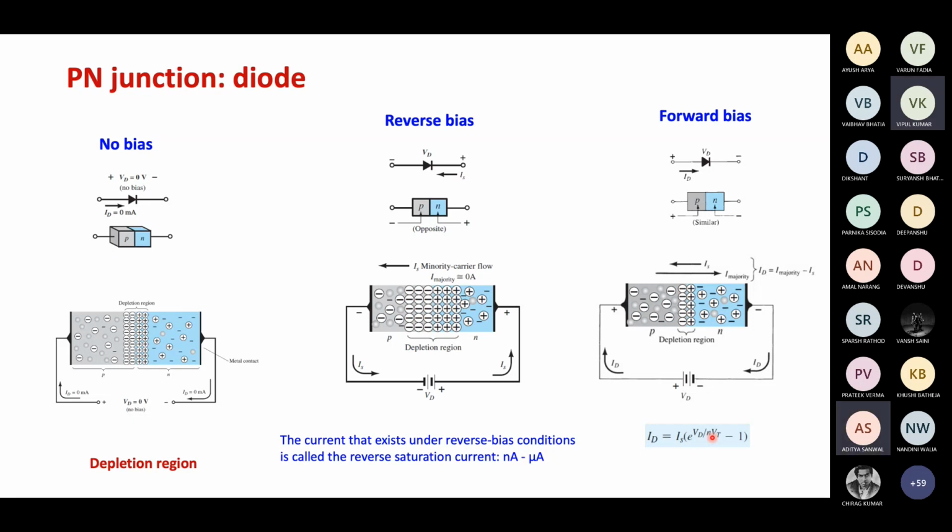So your question is, why is the depletion region getting large in this case? Yes, sir. This is because now these acceptor and donor atoms are uncovered. If we apply, for example, a positive voltage on the N side and a negative voltage on the P side,